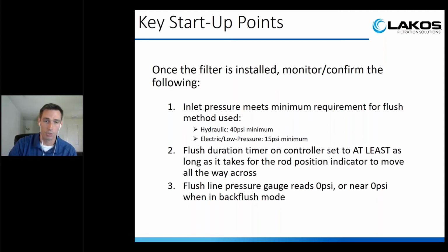So if you have a customer with the hydraulic version, but their inlet pressure is only 20 psi, that should be a red flag that it was not selected properly at the get-go. Hopefully that's not the case, but it is worth knowing that so you can help them solve their problem.